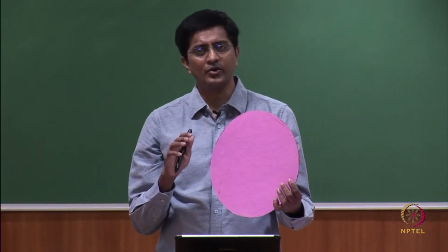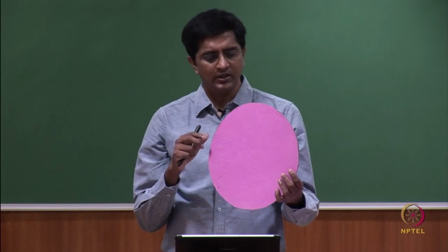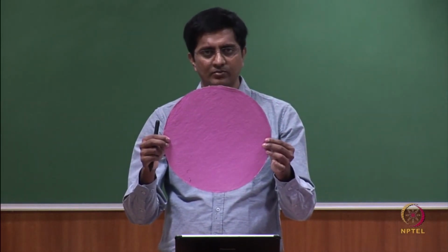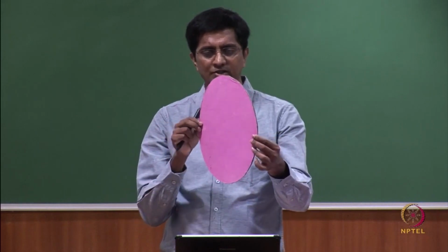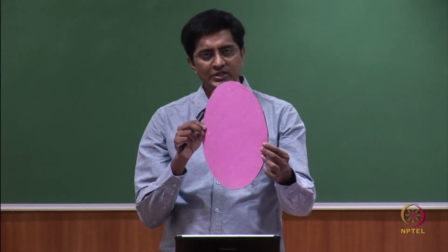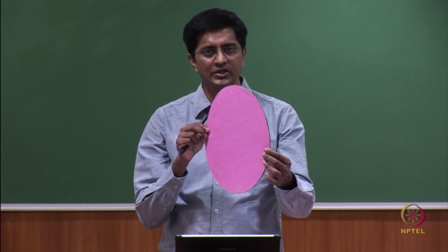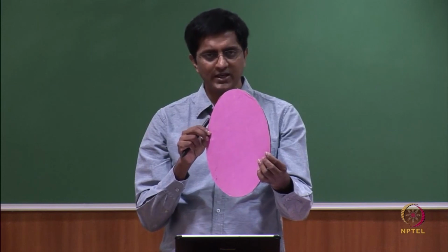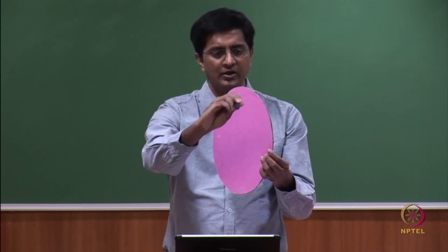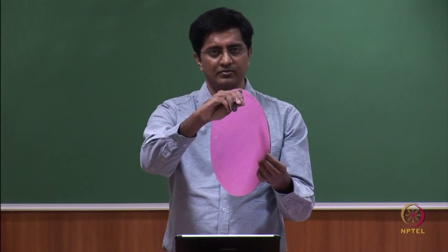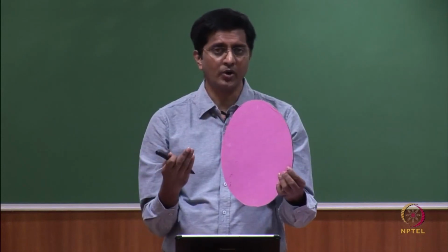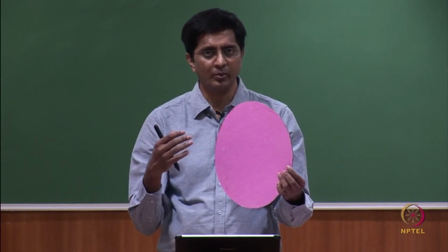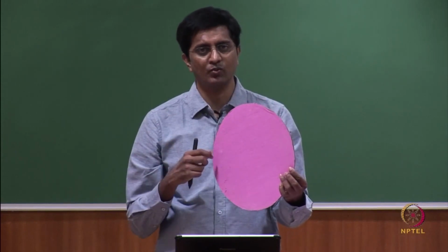Again, what I want to demonstrate here is, if you look at the front view, it is a circle. But the moment I change the orientation, will you still see it as a circle? Will you see the true shape of this circle? No. The answer is, at this angle, if you are looking from the front, what you notice is an ellipse. So, now you need to know how to draw an ellipse on an engineering drawing sheet, because you want to make sure that the ellipse looks very smooth.